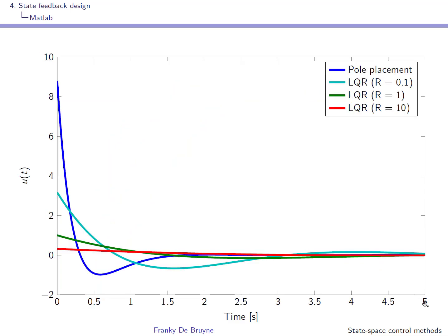When you do a design, you should always look at the control energy, so please do so in your control lab, in your report. Show the designs, but also show the associated control energy, and also put on the plot the saturation values. In this example we have worked without the saturations, but in practice there is always a saturation on the control energy.